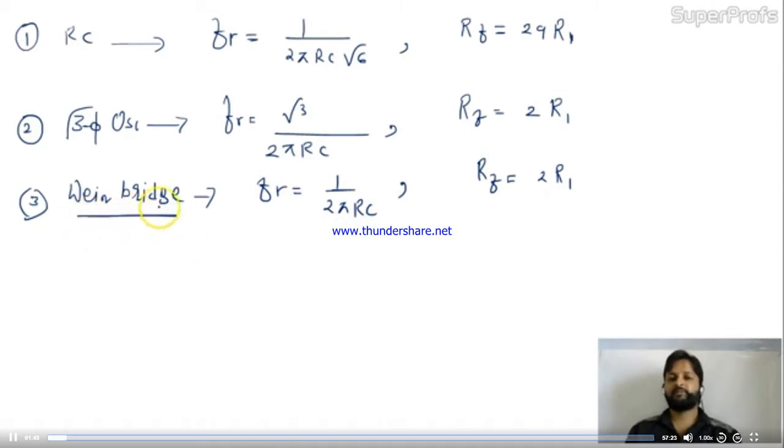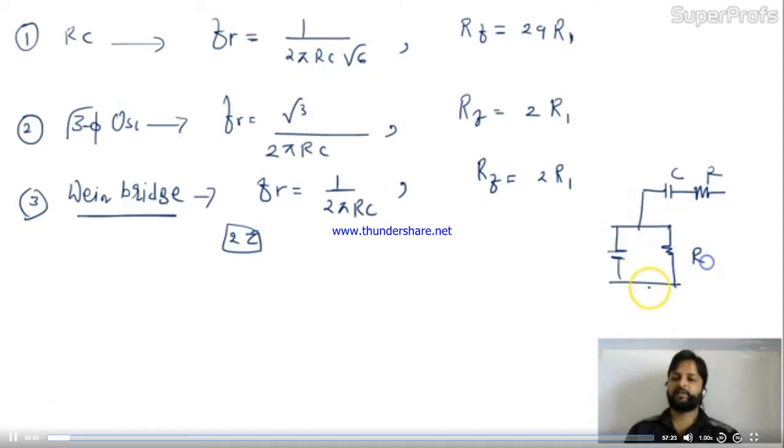That was the GATE problem in which they were doubling the time constant. Time constant means in the Wien bridge we are having two branches. In one branch you have capacitor and resistor connected in series, and in another branch the capacitor and resistor, they were connected in parallel. So they have their own time constants, let's take tau 1 and tau 2. So if you are doubling the time constant, definitely your frequency will become half of this, just half of this. Okay.